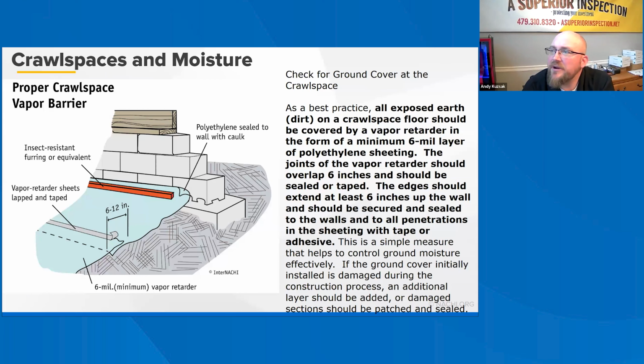The primary causes of moisture problems in crawl spaces are poor site drainage, lack of a ground vapor barrier, and ventilation during humid summer conditions. Crawl space moisture damage and mold formation can be caused by these issues and must be addressed for moisture-resistant crawl space foundations. Ideally, crawl space construction should result in an interior ground surface at or above the exterior finished grade. Extra attention is needed for foundation drainage with crawl spaces below the exterior grade.